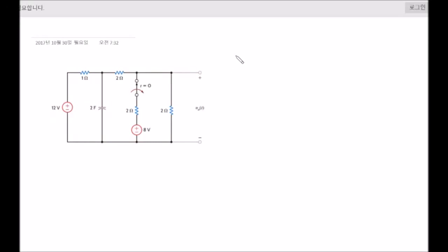Hello guys, another example on analyzing RC circuits. As with every other RC circuit, the first thing we need to do is to find the voltage across this resistor before time t0, when the switch is in this position. In this state, the capacitor works as an open circuit.